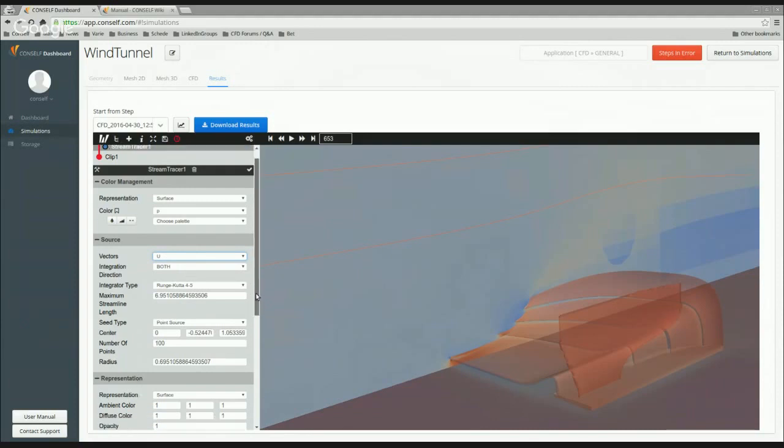Then selecting the source point. This depends on where you want to see the particles moving. So for our point of view in the graphical window, these values are okay. You have to do some trial and error here. Then you can just click OK and color it, let's say, with the velocity.